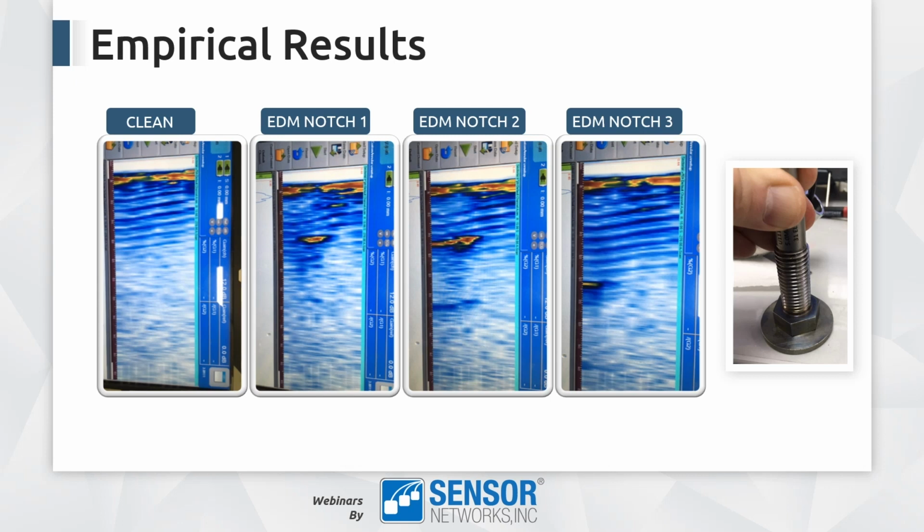Again, the idea of the modeling is to do that prior to prototyping, to get a good idea of your optimum design. So of the 3 that we chose here, we did modeling, we decided which was the most suitable approach, and then created a prototype. And this shows you some of the empirical results, showing the different notches. So again, a quick example, but it's just an example of the criticality of modeling and understanding what you're trying to do and how you're going to meet your goals prior to actually prototyping the transducer.